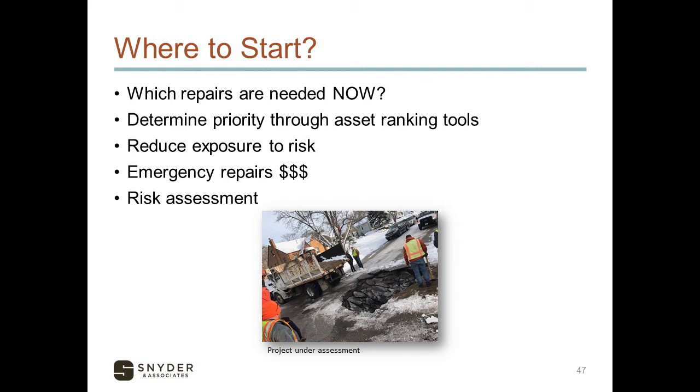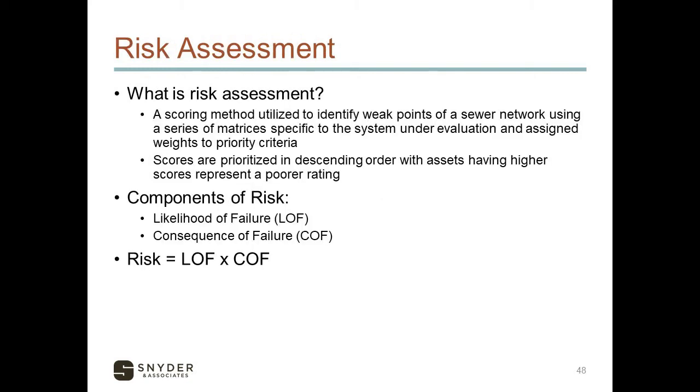I'm going to go into more detail on a risk assessment, which is combining what we're getting from inspection data to a more location-based type assessment, but using that assessment tool to help plan out where we want to start and where do we get the most bang for our buck, spending our capital improvement dollars effectively to help reduce risk. What is risk assessment? It's a scoring tool that we're utilizing to identify various weak points in our sewer system. We're using risk scores that we're calculating to give us a basis of where to start our rehab and create a guidance program on what the next steps are.